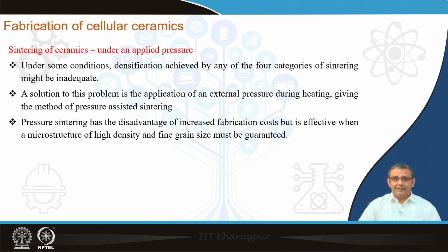But this pressure assisted sintering is a common process for bulk ceramic fabrication, and for porous ceramic fabrication it is very rarely employed. For porous ceramic fabrication it is mainly solid state sintering without an applied pressure, in a suitable atmosphere, that is commonly used.